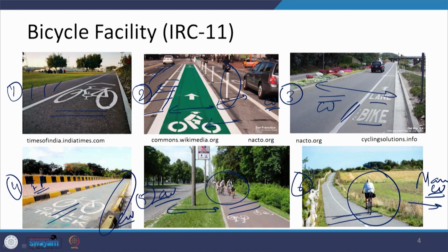So, if I go back, then what I can show you is that this is a segregated one. So, here the segregation is there. When I talk here, then this is an adjacent case. When I am talking here, then this is a separation case. So, these types of things can be there, and when we said segregated track, then this is a segregated track which can be utilized by the bicyclist, totally segregated track, or it can be a simple bicycle lane, and this can also be defined as a simple bicycle lane being provided here.